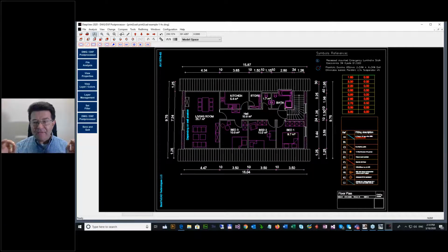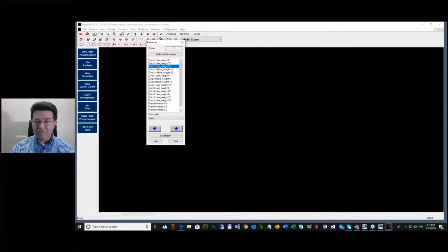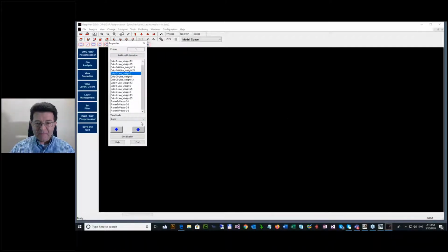These functions are made for the analysis of the structure of this drawing, because now you produce a DWG. You see, this is now a DWG. Now you can go to view properties, and you can see what kind of layers we were able to separate in this drawing. This drawing had no layers, and we try to separate every element from the PDF onto a layer depending on color and line weight. But here is a very important view. Now we view this drawing based on entity type.